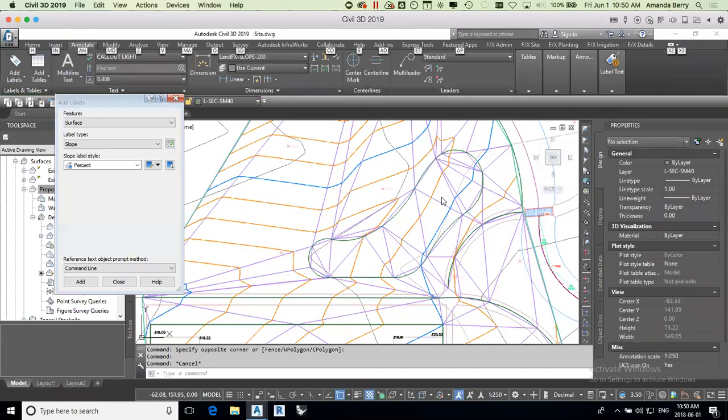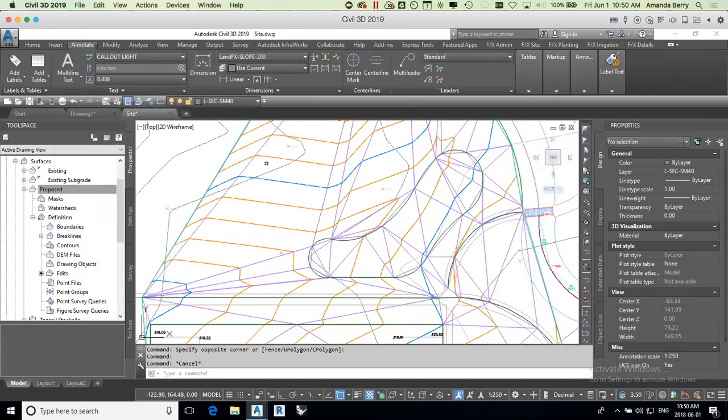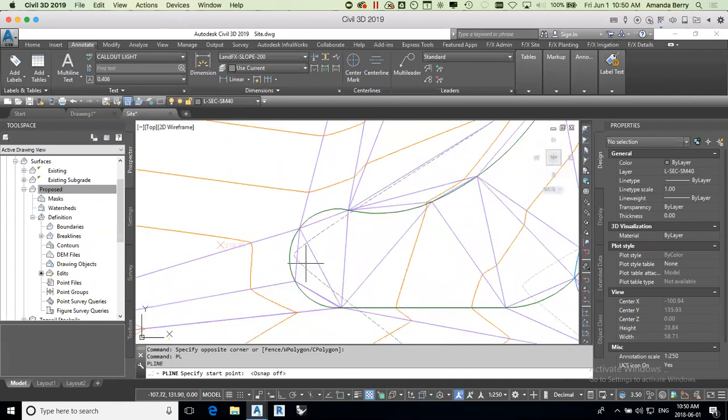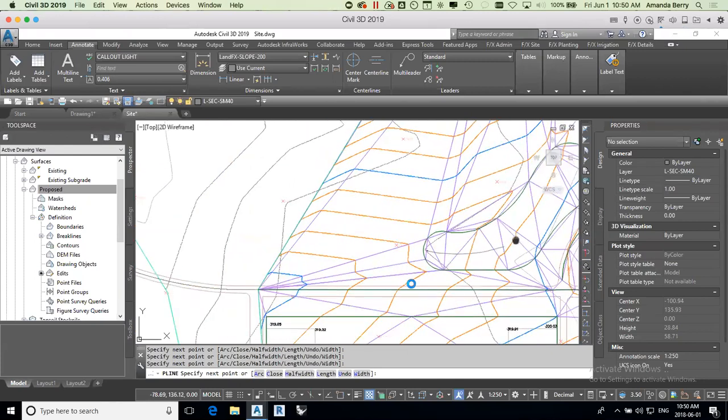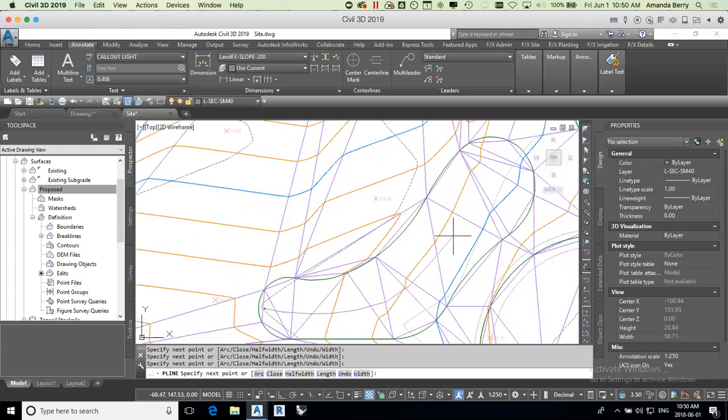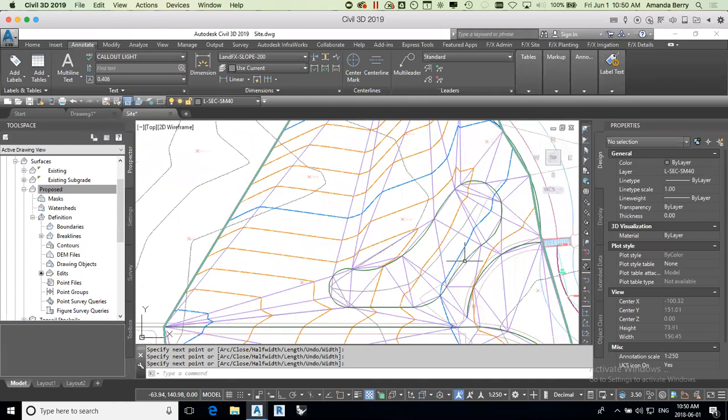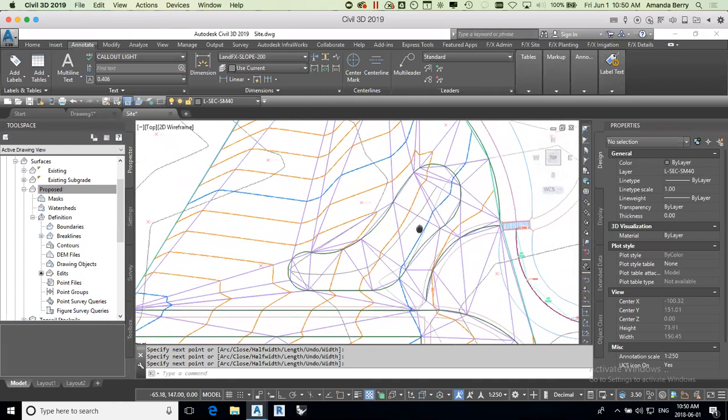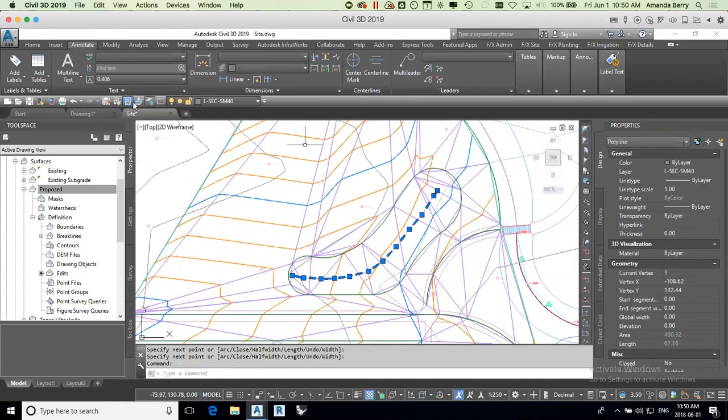But then what I do is I grab a polyline. Oh, I'm going to get out of here. There we go. I just draw a polyline in here, snap, and then kind of add a bunch of points. Sometimes I even like to offset this feature line in, depending on the kind of shape I want. Maybe I do actually want that really crowned shape at the top. You can do a lot of techniques with this, but this is one that I use.